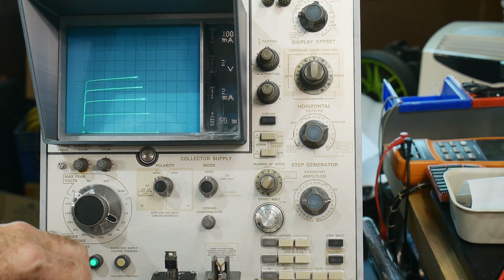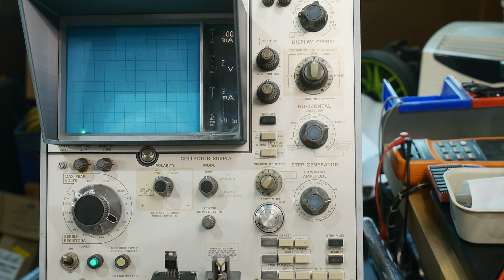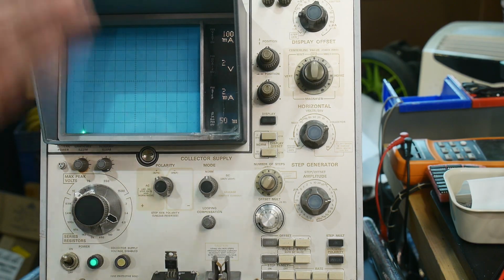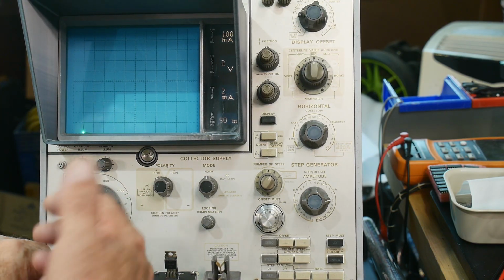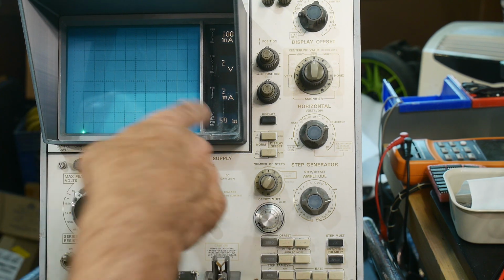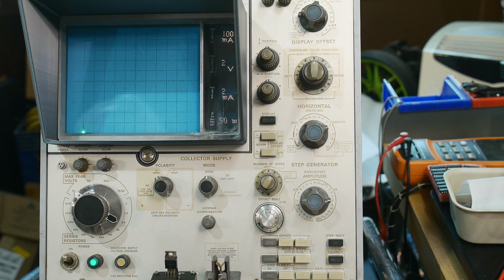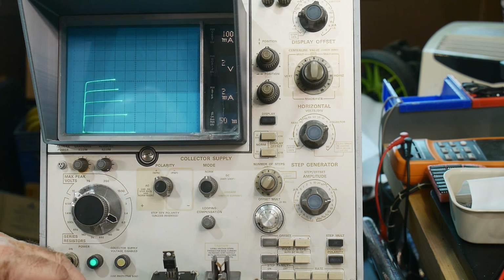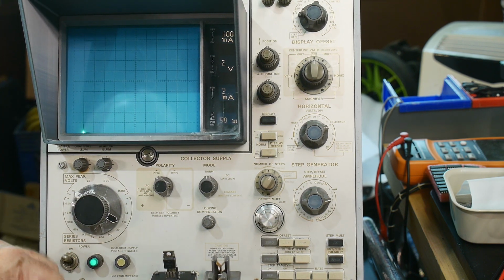And so you can test all sorts of things, high current things, low current things, and every transistor is unique. Some you want high currents, maybe you don't get as much beta. Small signals, maybe you'll get more amplification. So you need to choose the settings and the conditions of what you're using in your actual circuit.